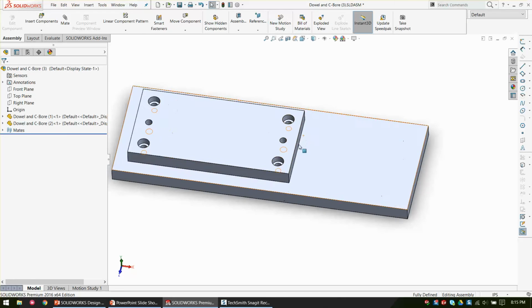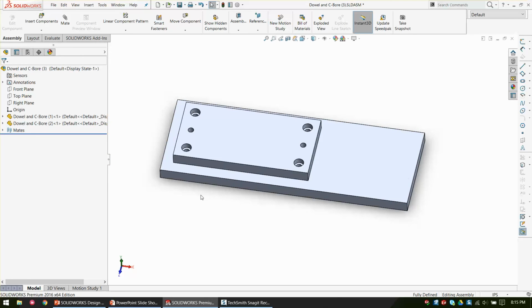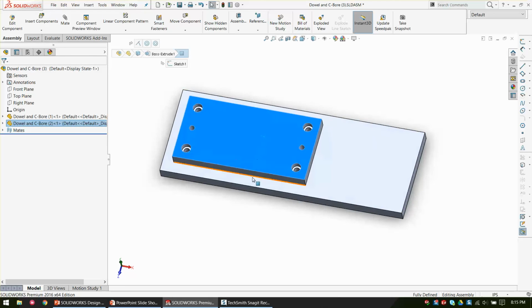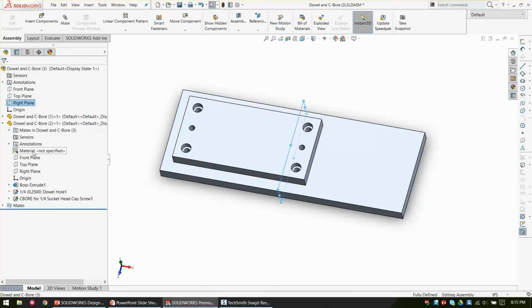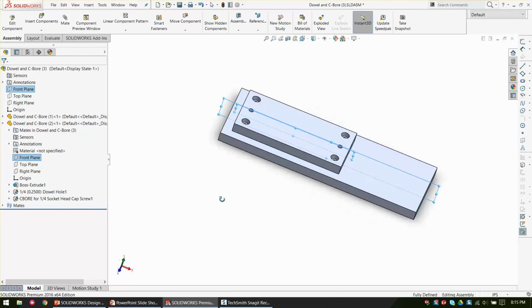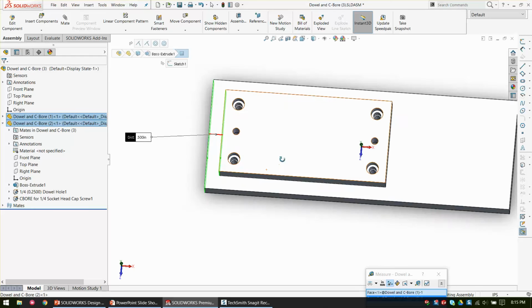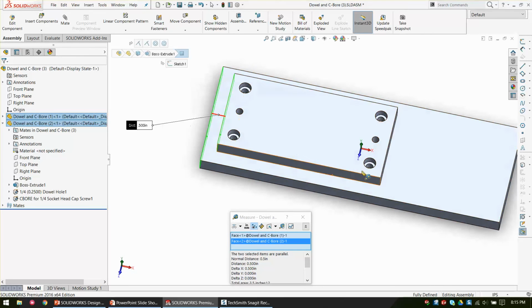All right, so in this instance, it is possible to mate this block multiple different ways, right? We can all list a number of ways to mate it. I could mate it with planes, because I did good design intent, in my definition. Again, anytime I say this is my definition, my experience. I could have done planes. I could have done a distance mate and said from here to there, I want you to be so far. Could have done lots of things. And if I had mated planes and faces, then no matter what I changed the holes to, it would always rebuild. It would never throw an error.